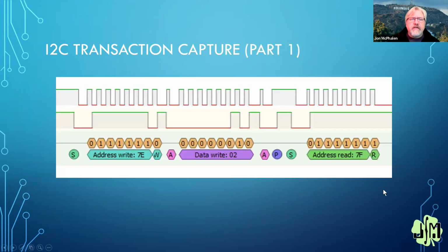So here you can see the details of the thing. Now, interestingly, you'll notice that when you do a read from an I2C device, and I'll show you this in the EEPROM driver, you actually do a write, and you write the address you want to read from, the starting address, and then you restart the condition in read mode. So you can see here's an address write.